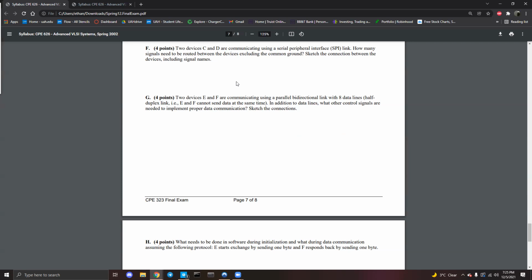And SPI also has this nifty little feature called multiple slaves. Well, yeah, slave select enable. Yep. So you'll have to have a line to select which slave device you're talking to. When I think of that, I think of it as like a letter with an address.